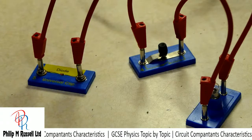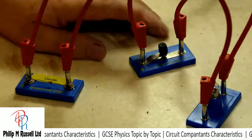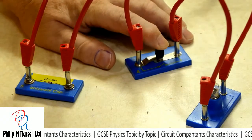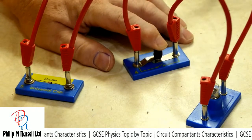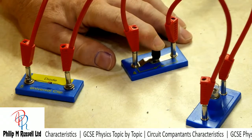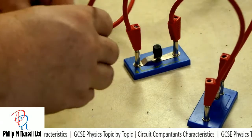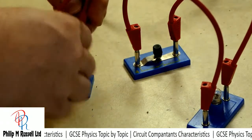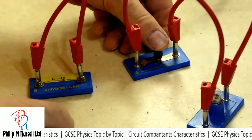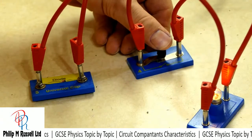So back to the circuit then. We've got everything set up, and if I switch on, then nothing is happening. What happens if I turn the diode round? And now the bulb is lighting.